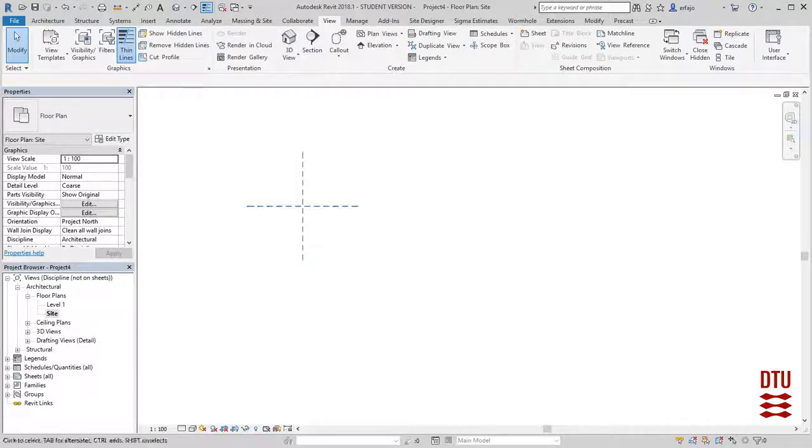These two points are normally the only points which are shown in Revit, but the most important part is actually the initial one, because the initial one is the one you can use when you export your drawings or models to AutoCAD drawings. If you don't know where the initial setup, or the 0,0 in the drawing or in the model, is, then you will have wrong places, or you will export them wrongly, so they will not be able to be put together properly.